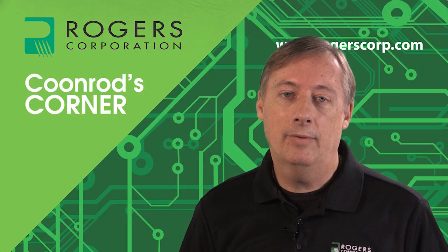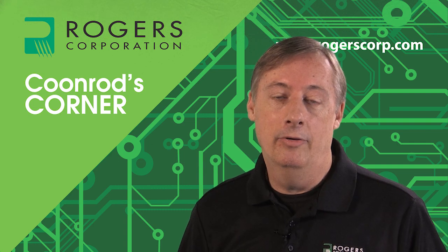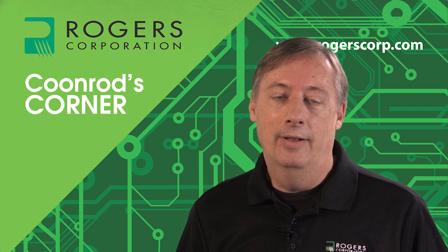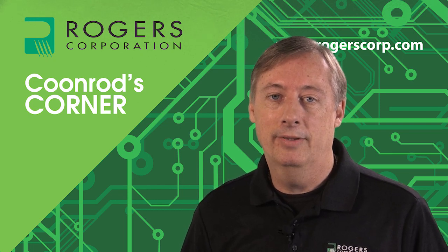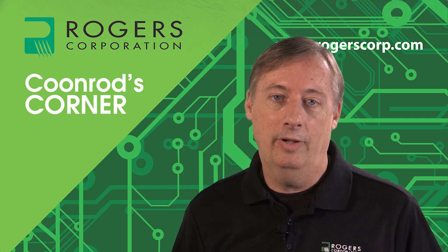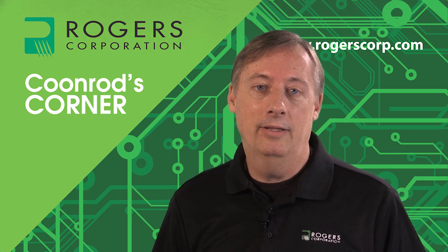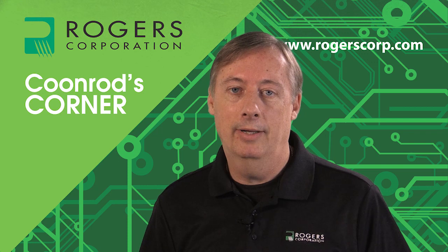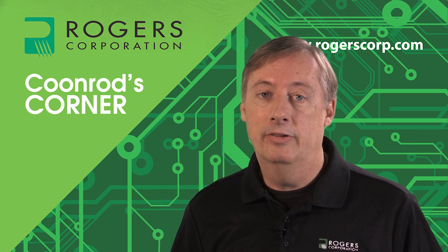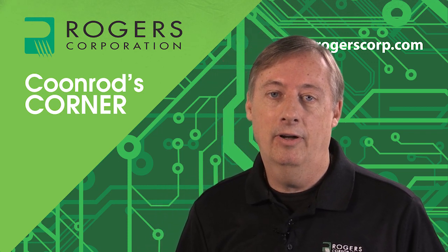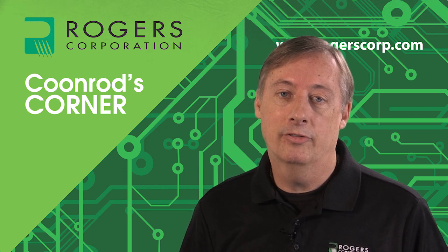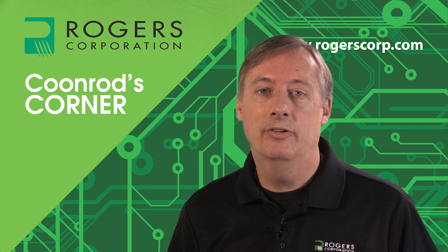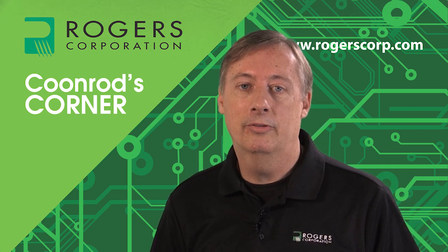In summary, I've shown several different variables that are normal variables in building a circuit that can impact RF performance. These variables can be copper plating thickness variation, trapezoidal effects, plating. There's several different things, and these are items that you really should talk to your circuit fabricator about to understand to what degree these different variables can actually alter the performance of the circuit itself. And you should also talk to your material supplier to understand what kind of variation is normal for some of the properties of the materials.